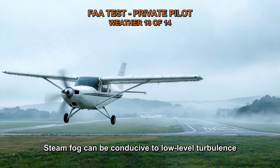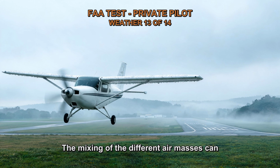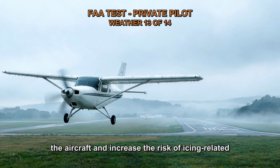Steam fog can be conducive to low-level turbulence because the temperature contrast between the cold air and warmer water can create unstable atmospheric conditions. The mixing of the different air masses can result in turbulent airflow and gusty winds near the surface. Additionally, steam fog can pose a hazard for aircraft icing. As the cold air comes into contact with the warmer water vapor, the moisture can freeze on aircraft surfaces, leading to the formation of ice. This can adversely affect the aerodynamic performance of the aircraft and increase the risk of icing-related issues.